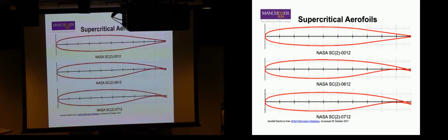Now, what that means is if I draw the camber line on this one here, it's pretty straight through here, and then gets a big curvature at the end. Remember, the big curvature in our camber line is where we generate our lift, so we're aft-loading our lift. And what that means is that we get very little difference in forces here and a lot of difference in forces there. What do you think that does to the pitching moment?